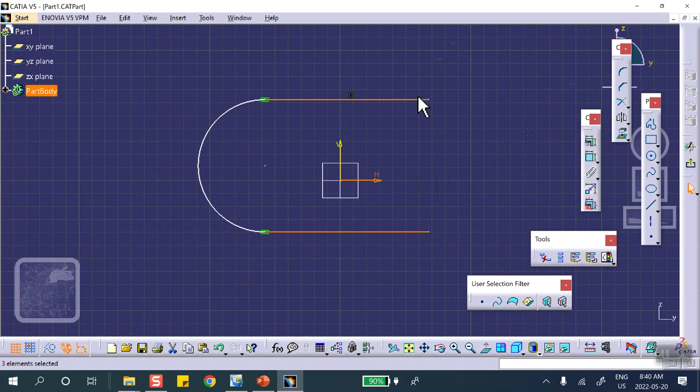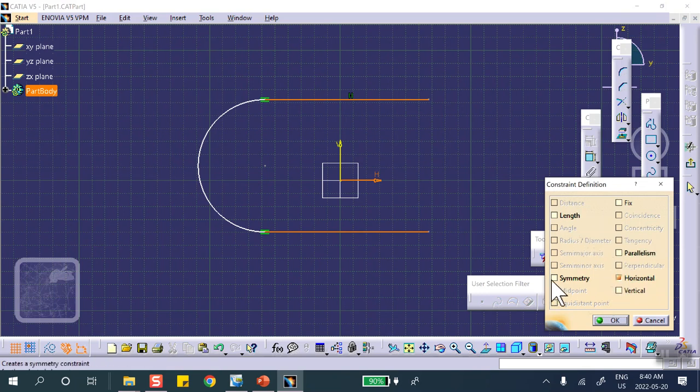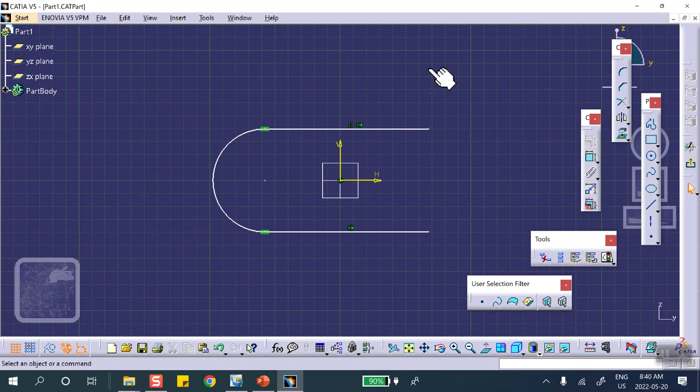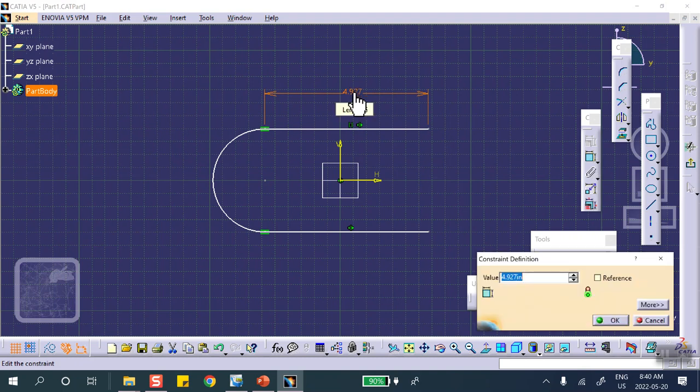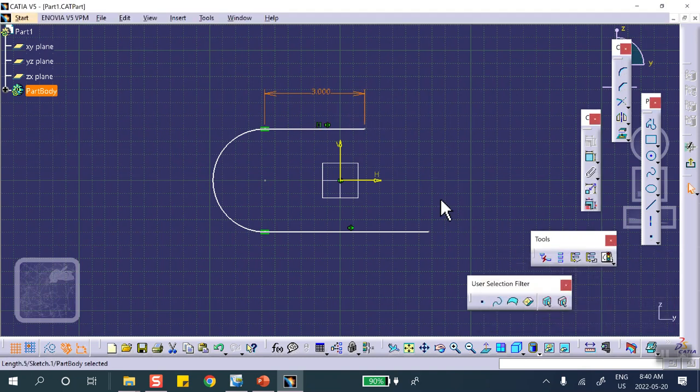Okay, clear up. So this guy, constraint using dialog box, you make it symmetric. Very good. And I'm going to put some dimensions here just so that it looks similar to what we had before. This, I think, is 3 inches. 3 inches. Okay, so that one, control this point, coincident.